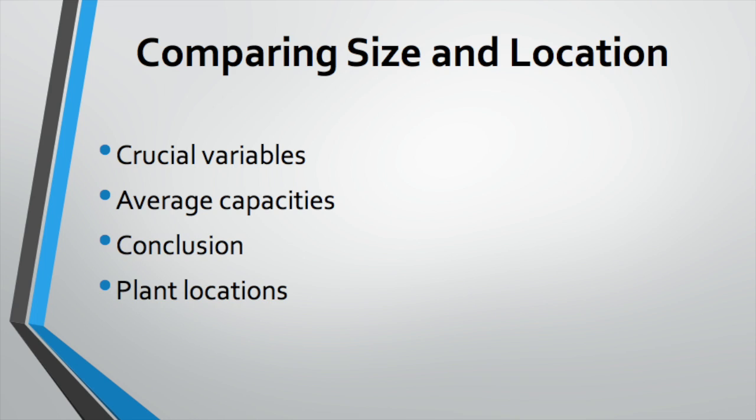It is also worth noting that RO is a much more flexible technology and could also be utilized with a brackish water feed stream. After all is considered, analyzing the data shows that MSF plants are capable of being designed with a higher capacity compared to RO plants, while RO plants are much more flexible as they can be designed to maintain a capacity as low as 100 meters per day. It is irrelevant to declare either method's capacities as better or worse, for each type brings its own advantages and could be applied to different situations. While both MSF and RO plants can be installed in a variety of places, both are most common in areas where potable water is not easily accessible.